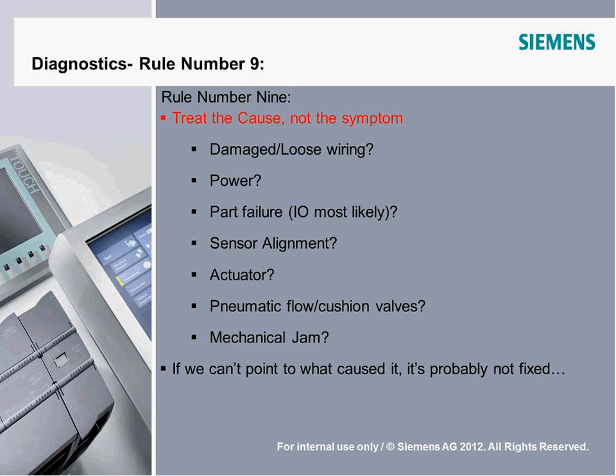If you're looking at a cylinder extend and come back, check those sensors at the ends. Certainly if a cylinder is all the way extended when you show up and the machine's stuck, then hey, take a look at the extension sensor. Is that on? If it isn't on, then it's probably a good chance that that's what's holding up the machine. Actuators, those are mechanical, electromechanical devices. They can have problems with their coils.